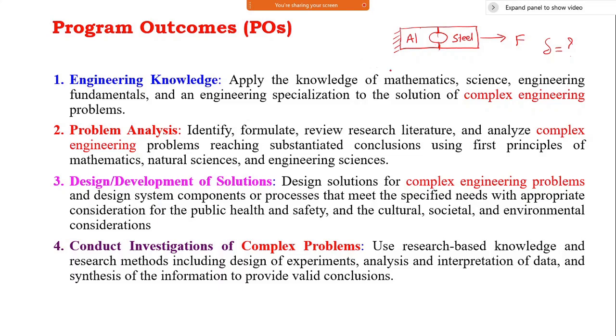One more complexity I can provide now. This force was a fixed, constant force. I can give this force as something sinusoidal, and then do the analysis. Again, it improves the complexity. Then instead of this sinusoidal force, I will give a random force like this. And I will analyze how much stress will be generated, what the deformation will be, what the shape of my vibrations will be, and everything. So that is complexity.